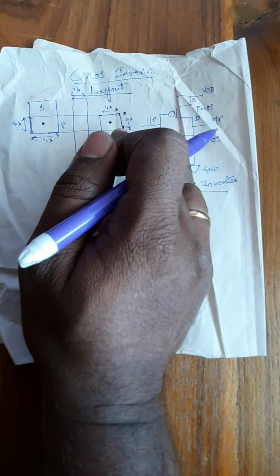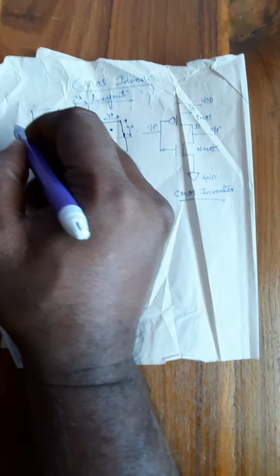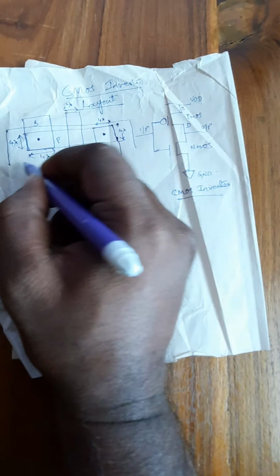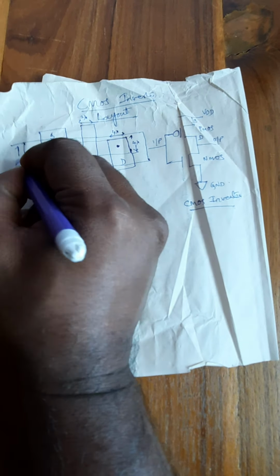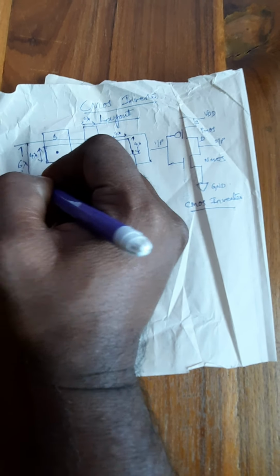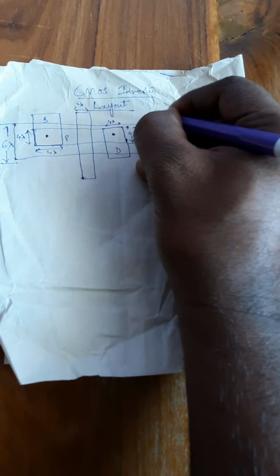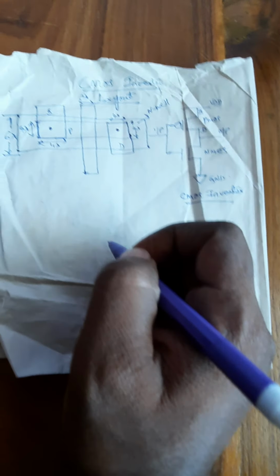Once you complete the source, drain and gate terminals, on top of this particular layout you are supposed to draw a layer of width 6 lambda and variable length, which encloses the layer we have drawn just now. It is of 6 lambda width, and it is an N-well. So now we are drawing our CMOS inverter with the help of N-well technology. So this is an N-well technology CMOS inverter.